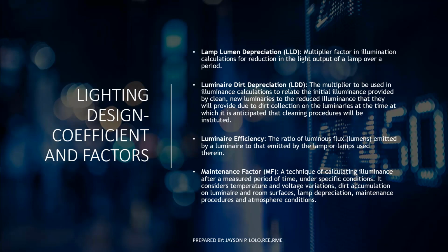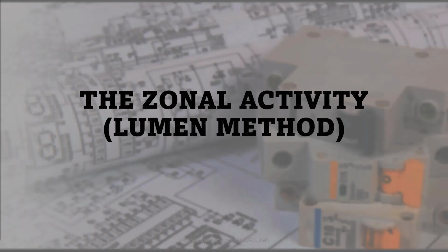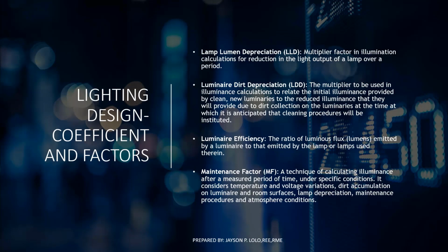Generally, light loss factors are divided into two groups. The first is recoverable. Remember that some lamps are recoverable, so you can clean them. You can also replace the lamp, which is what we call relamping. And the last one is if the fixture itself or the lamp itself cannot be used or recycled, and it is under the non-recoverable part.